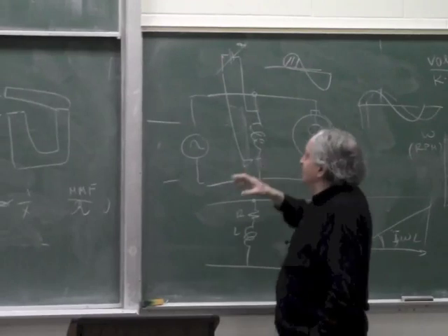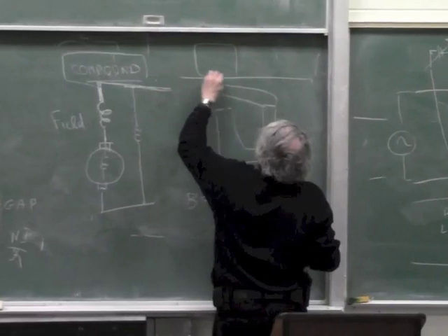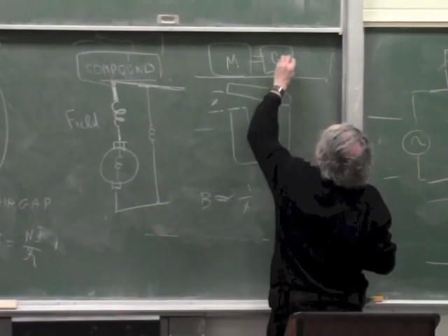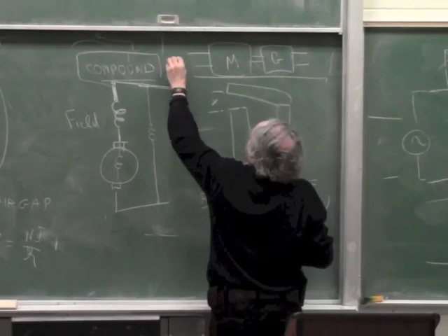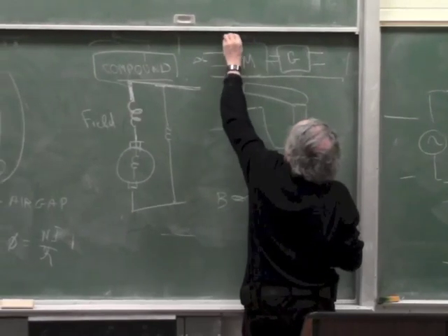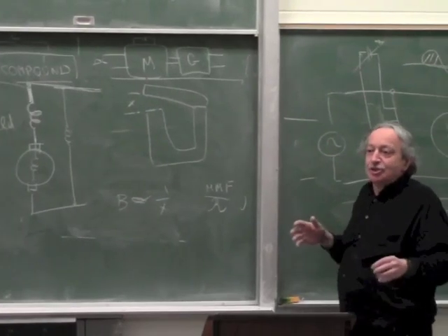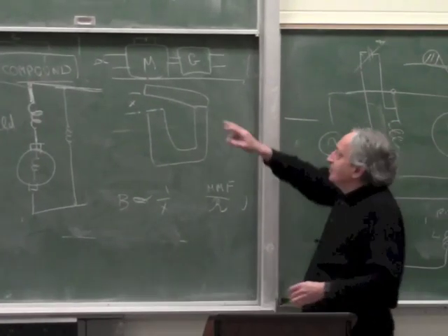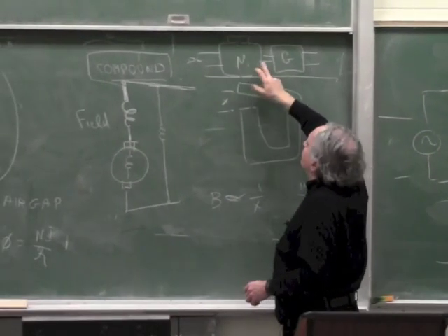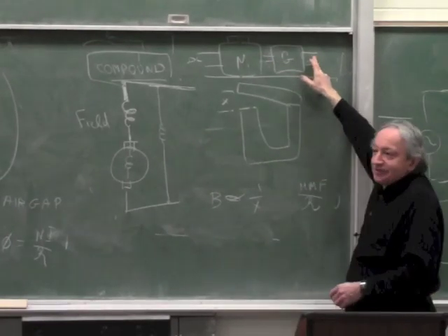Okay? So imagine if this is a motor driving a generator. This is motor, this is generator, and you put in some DC power here, and you can control the field of this motor. Okay? What you have is an amplifier. The amplifier can generate many kilowatts, because here you control with a small current the output speed, and the output speed controls the output voltage of the generator.